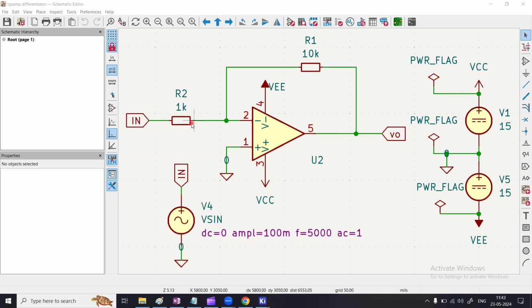input, currents at the input pins, and the current available to be delivered to the load from the output pin will be available through the operating point analysis. Also, you will see how much total current this circuit is drawing from the power supply voltage supplies there. And based on that, current multiplied by the voltage will give you the power consumption. So let us do that.